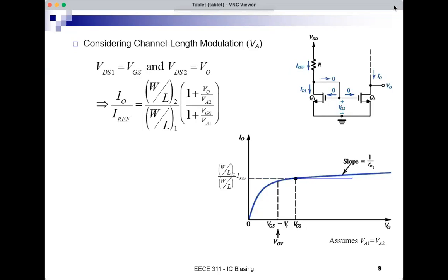So this ideal line is horizontal. What does this mean? It means that current doesn't change. It's at this fixed level. So if the current is at this fixed level here and does not change with voltage, that would be an ideal current source. So horizontal is the ideal.